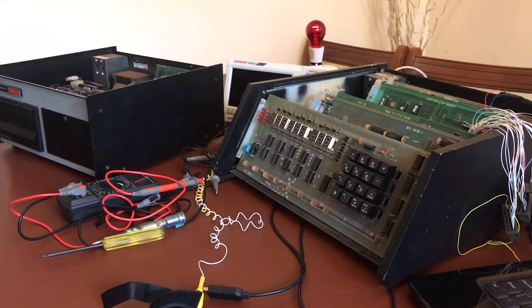It just seems to be really lucky that the RAM fault is in an area I was in, the top bank of the 4 banks, and so in the top 4K chips. But it wasn't actually present in the rows at the very top of RAM which it picks to become the stack. So by pure dint of luck, the first 3 banks of 4K run fine and test okay, and the top bank didn't. What I've done is I moved the faulty chips to the 3rd bank, and each of the addresses moved with it to the 103 range.